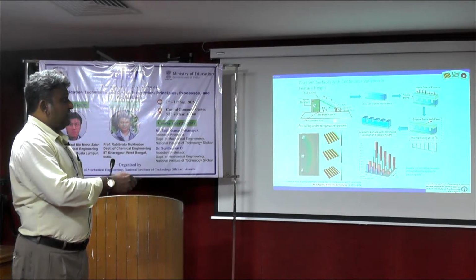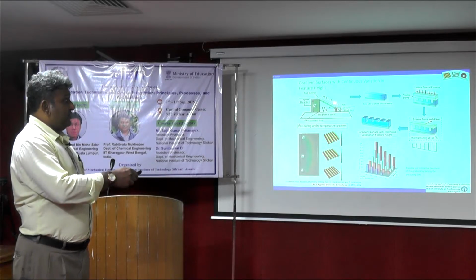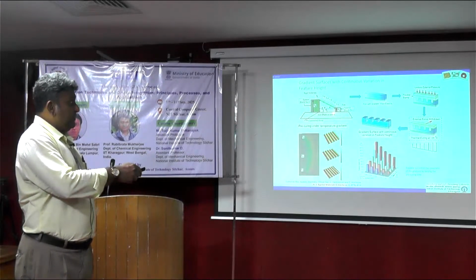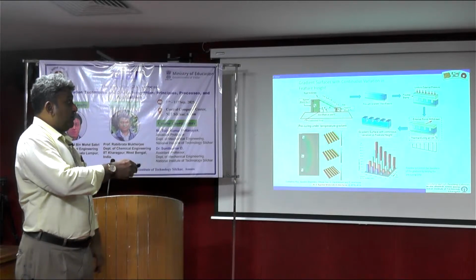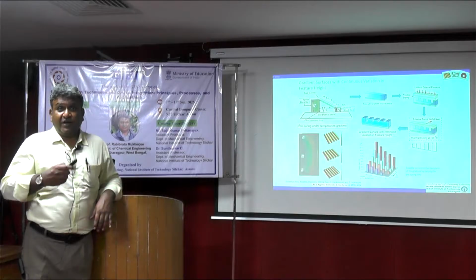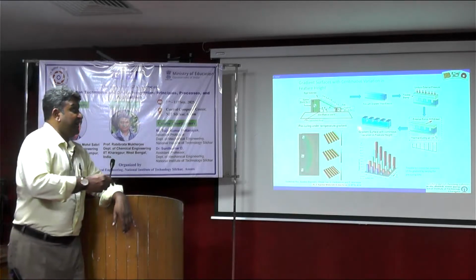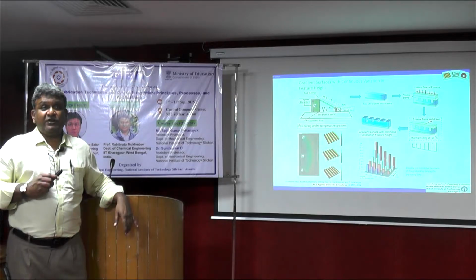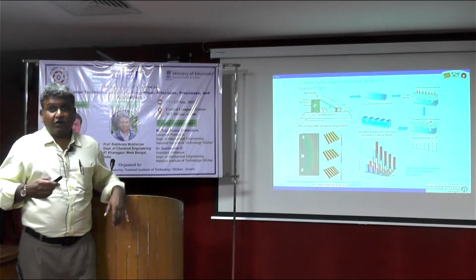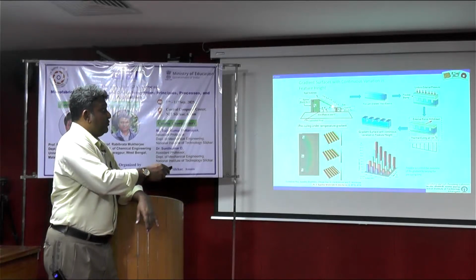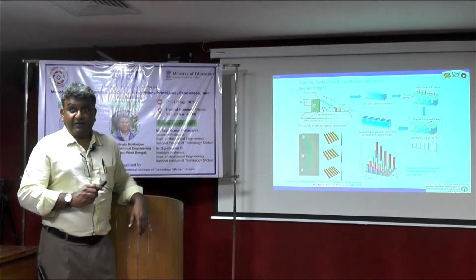Now this is the heat source. Here is the film, the blue colored thing. This part of the film is closer to the hot plate. This part of the film is further away from the hot plate. So now I guess all of you understand that this area receives more heat flux as compared to the other area. And what is the consequence of that? The consequence is this part becomes more elastic as compared to this part.